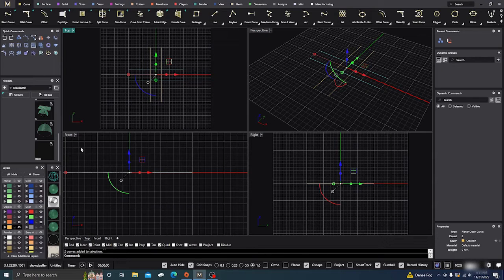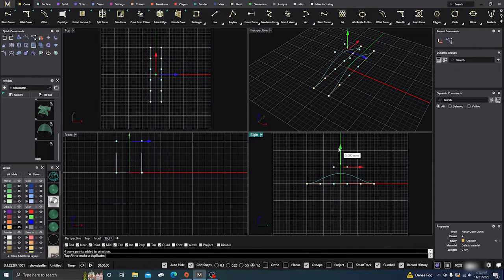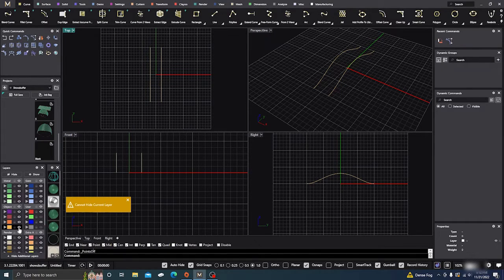Again, I'm going to take 2 of those curves and put them on gray, and then for right now I'll just hide them. So we'll just deal with these 2, and we'll turn on points. And I'm going to go ahead and take these 2 in the center here and then drag them up something like that, and go ahead and accept, hit F11, turn off my points, and we'll go ahead and hide them and bring back our other curves.